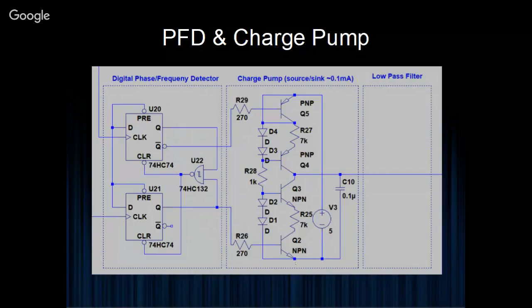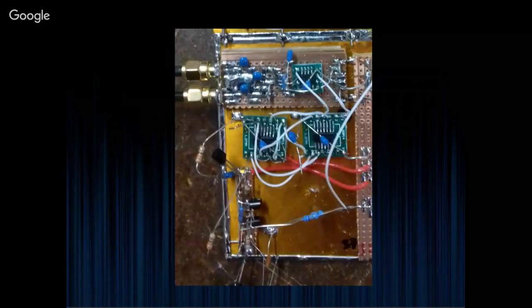So what you end up with is effectively a phase-controlled integrator, and that integrator will then control the frequency drift of your oscillator. Normally this signal should be passed through a low-pass filter. I didn't have time for it, and it still seems to lock within a narrow range, so I moved on to doing the presentation. Here is the zero crossing detector.